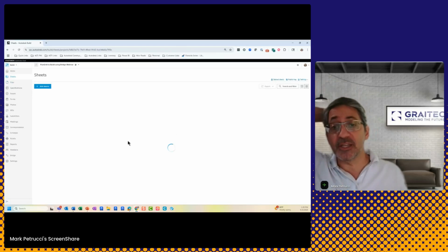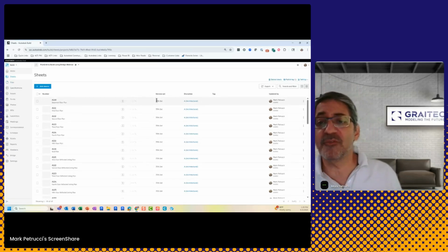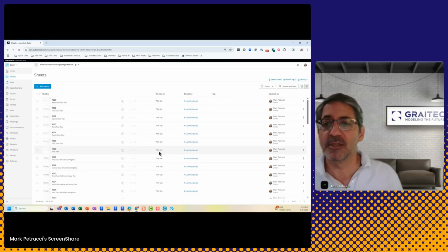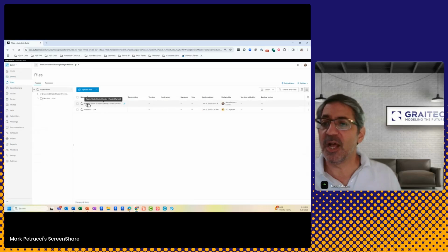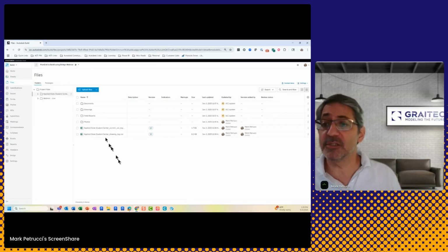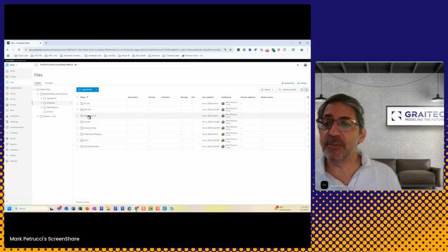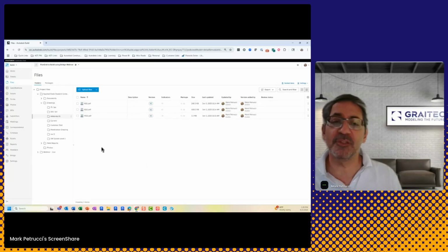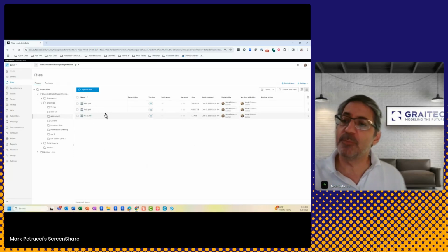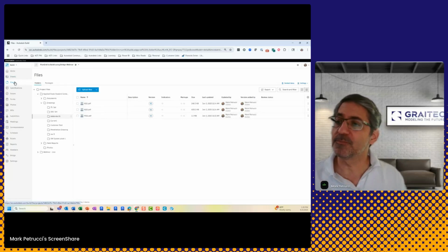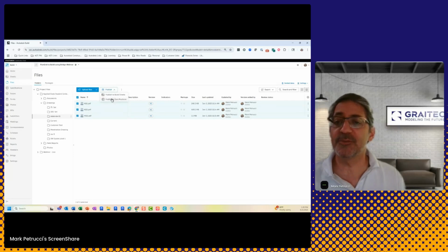Now, I've already done it one time for my 75% set. I'm going to show you how I'm going to do this for the other set. So I'm going to go back over into Files, and I will select the PlanGrid project. I'll go to Drawings, and I'm going to select on Addendum 1 because there's only 3 files in here. If I want to push these over into Build Sheets, I'm going to select each of them. I will hit Publish, and you'll notice the option that says Publish to Build Sheets.